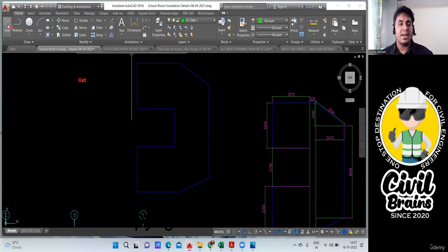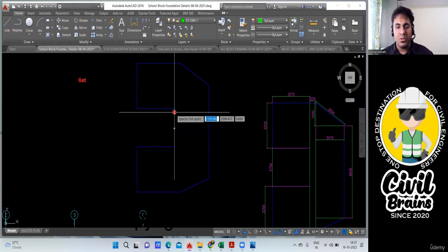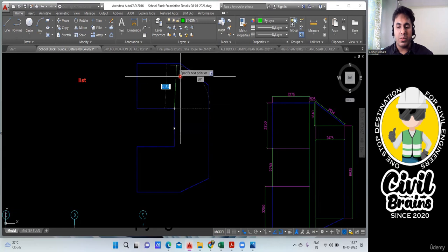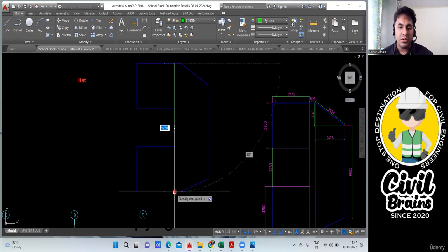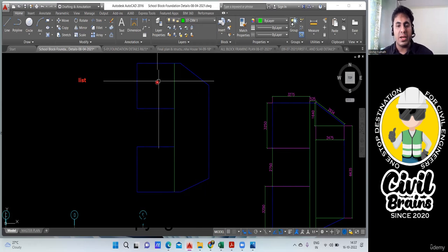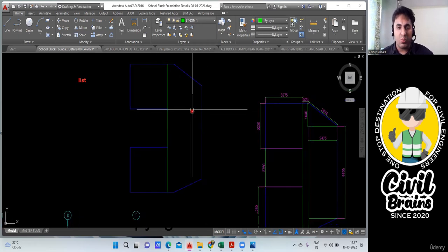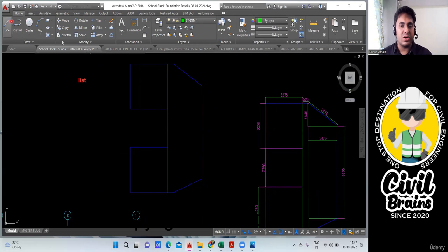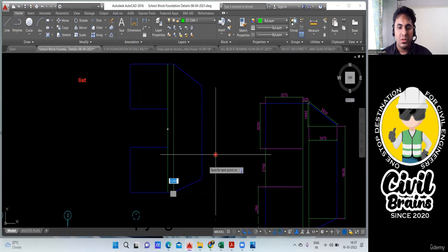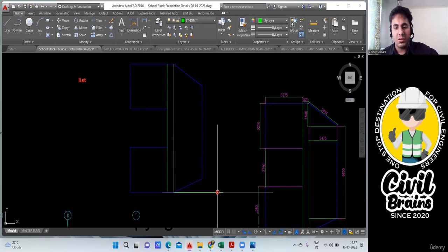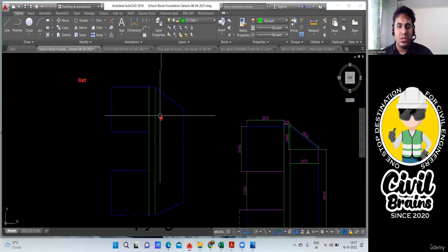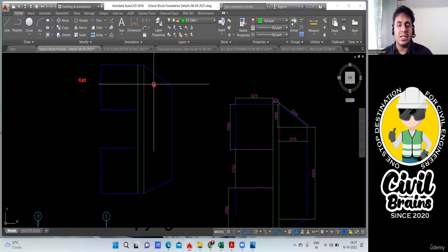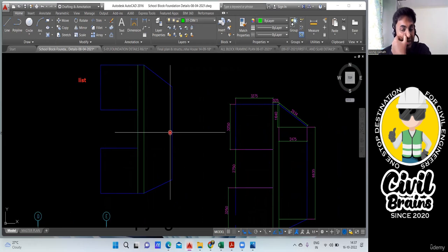So what I'll do, I'll take a line command from here. Let me try to make this as one part. So this part and this part. Now this got converted into square and square. Then again, here you have a small portion. This portion I'll convert again from here to here. This is another portion. Converted. So this is also a rectangle portion, square portion. This is a kind of trapezoid. So you can directly keep a trapezoid and apply the trapezoidal formula. That also can be done.